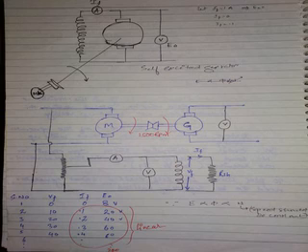Now listen. This is the field resistance line. If you have a point here and you want the resistance value, you take the voltage across this and you take the current. V by I gives you the resistance value, yes or no? Similarly, you have a point here and you want the resistance value of this line. You will extend like this: length of RT in volts by length of OT in amperes. V by I. What is this? Critical resistance.